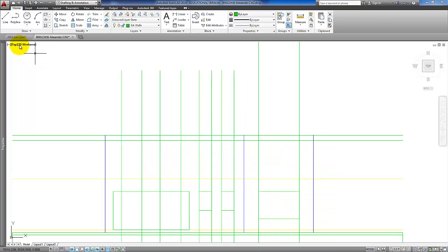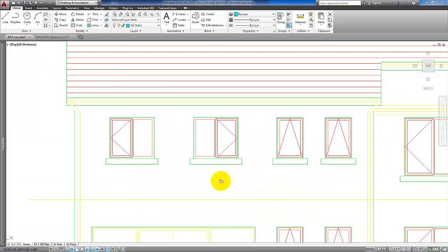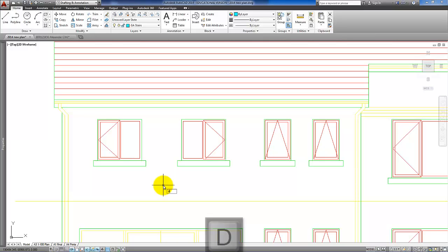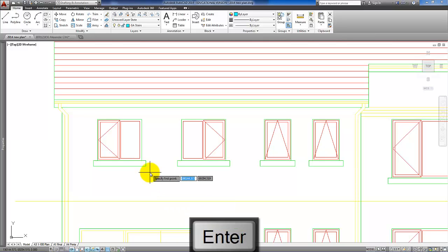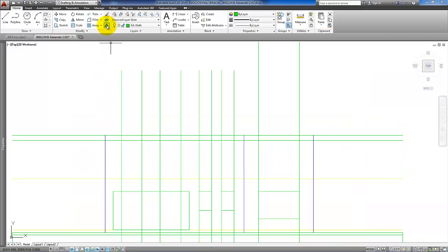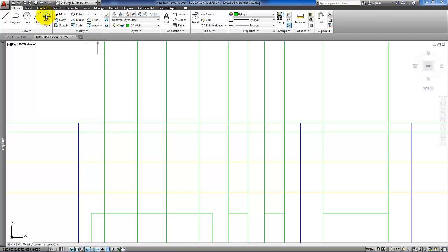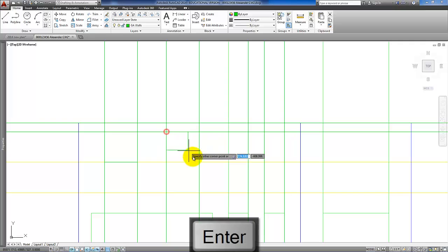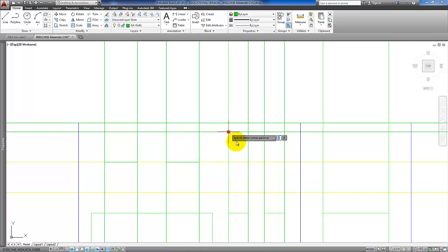And then when we're drawing these in, we need to compare the window heights here. So let's just take a dimension on these windows. The four windows on the front are all the same at 1050. So offset 1050. And then we can draw in the rectangles just representing the position of those windows, nice and symmetrical there with those two windows above the ones on the ground floor.